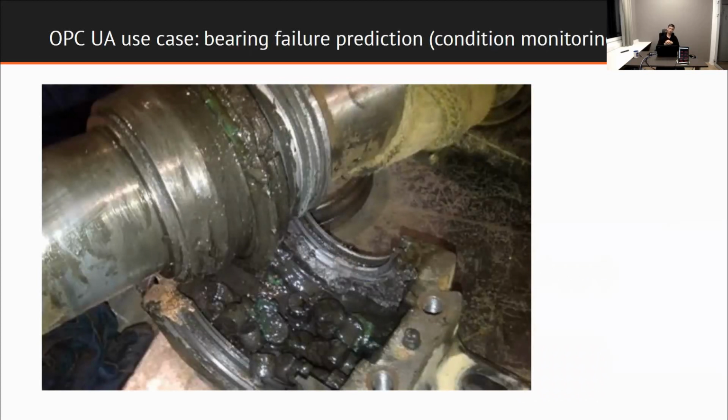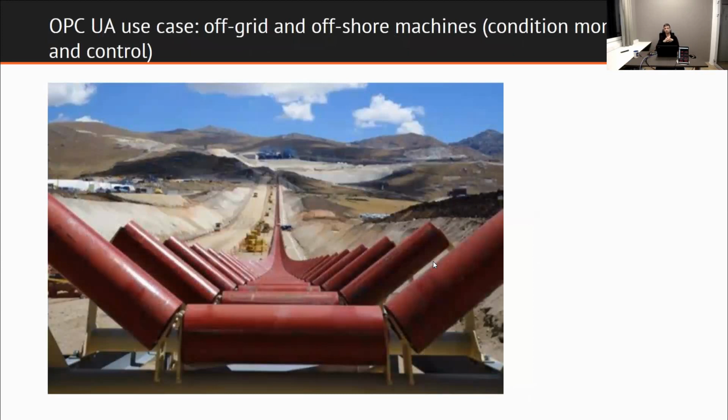Condition monitoring on the bearings by measuring noise, vibration. This is another possible application. With analyzing data coming from sensors, we can effectively prevent failure. We can even predict time of probable failure. In the end, we prevent damage and reduce downtimes. And this means huge cost savings for us.